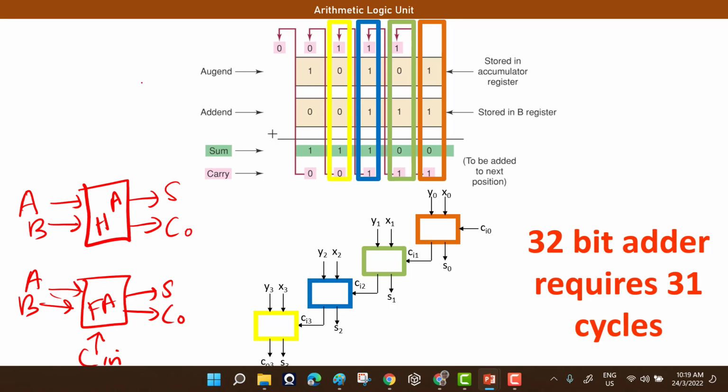When you want to do addition, the process very much depends on the number of bits the number is representing. In one exercise that we did, if we were to add only 1 bit numbers, it will be A plus B, and you will get your summation, whether there is or is not a C out. Why do I use the words whether there is or is not C out? If A is 1, B is 0, for example, you will only have sum, you wouldn't have C out.